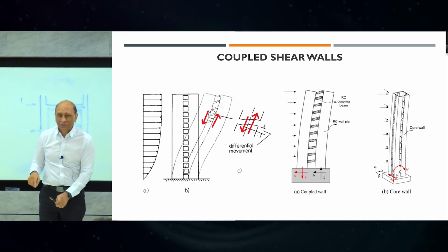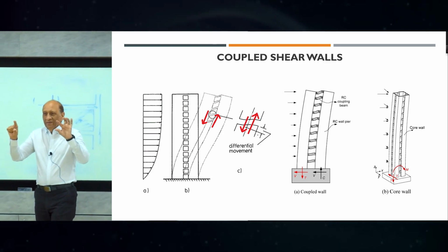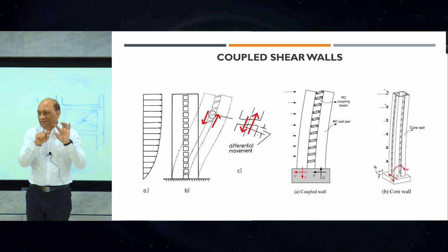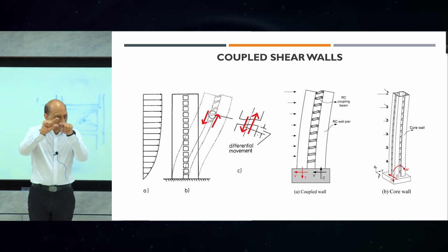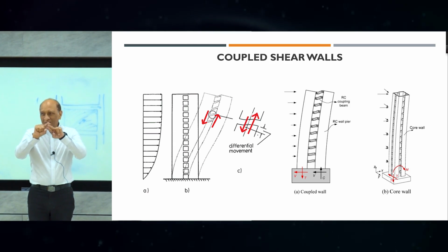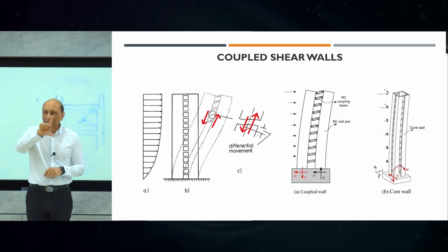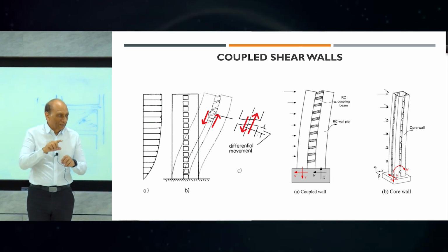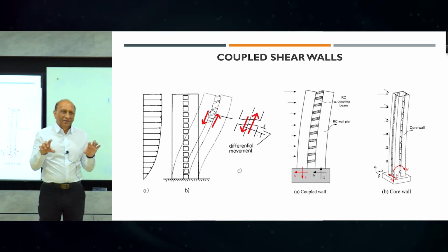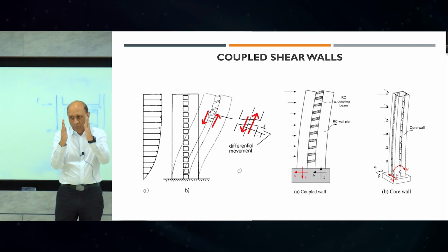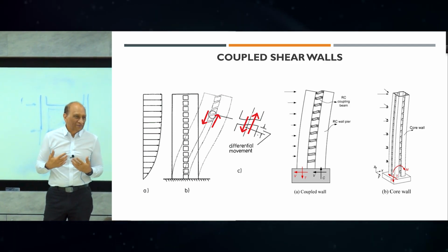Remember, I just explained to you a few minutes ago that in a lateral load, the moment is created in the beam first, and shear is created because of the moment. So if you limit the moment, you can limit the shear. So you can allow it to yield to a certain level so that it will not fail in shear. So it will become like a ductile beam with a certain capacity. It will resist the movement until some point, then let it go, but will not break itself, right?